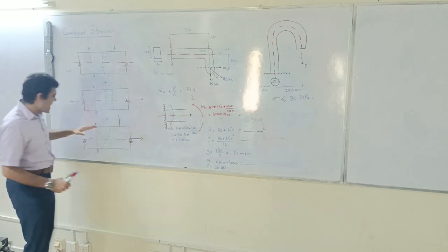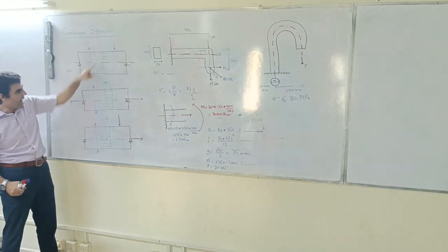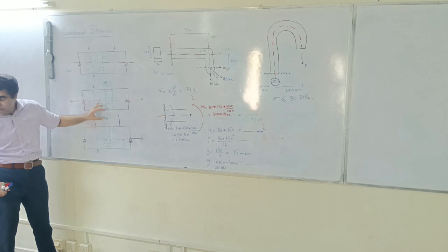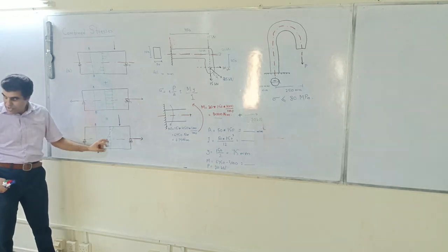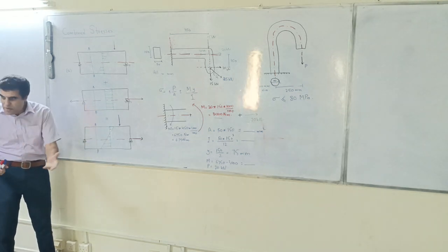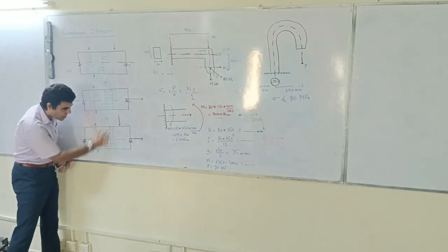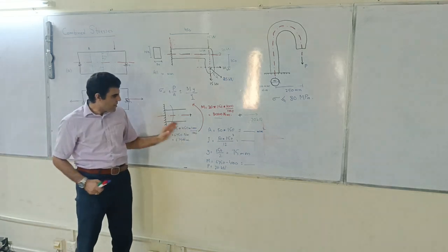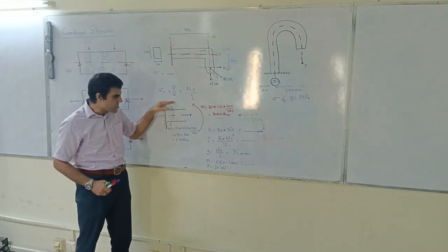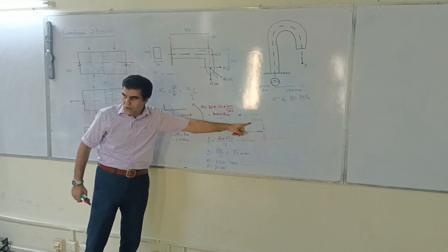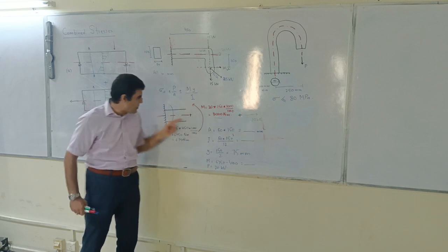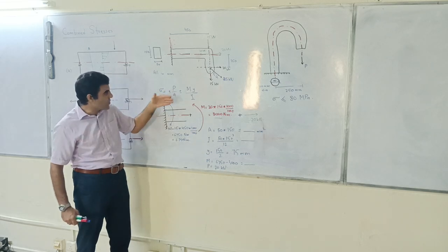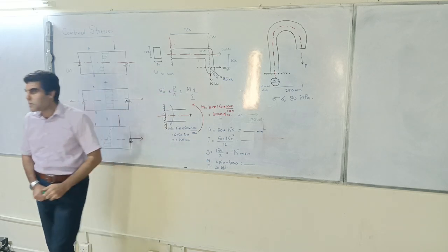This is the same thing as we did over here. We had a compression and we had a tension. So this tension and this tension, these both added up and we got a bigger tension. So if you are asked to find out the maximum stress at the cross section, you will give this one, not this one. This moment has got tension above and you have got tension load applied over here. So above the neutral axis, that is the maximum stress. You will just plug the values in this one and you will get the maximum stress.